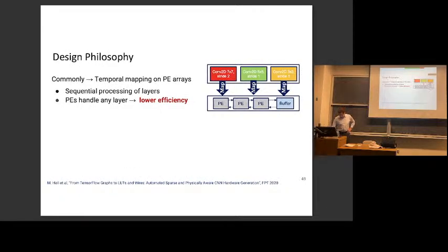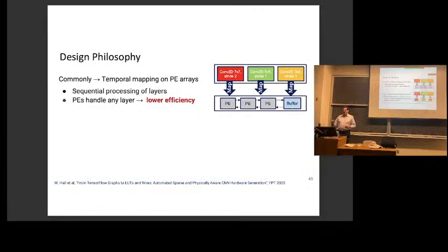And so on. We go on to the next one, and it's got an even smaller filter, a 3x3 kernel size. So that's one way we could build our hardware. We could build it with these more generic PEs. We want some parallelism, so we usually build a whole bunch of them communicating, and they have enough flexibility, which basically means muxing or sometimes extra hardware that's only used sometimes, so that they can do any one of these layers. Okay, but that costs you some efficiency.